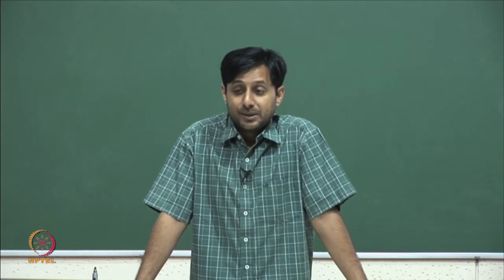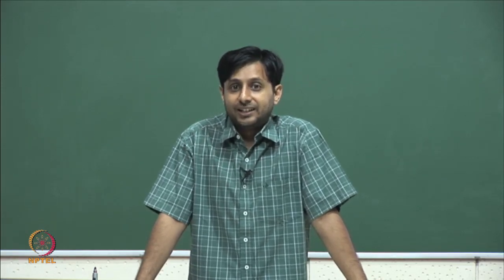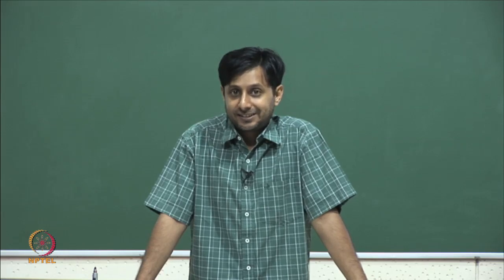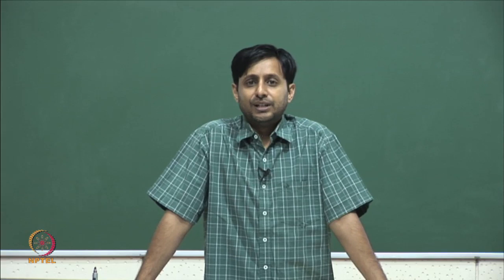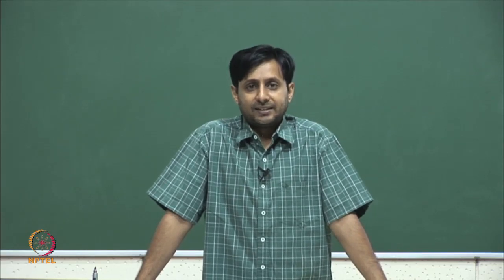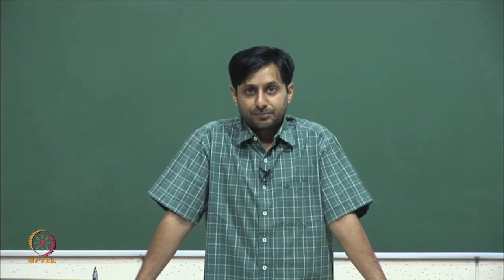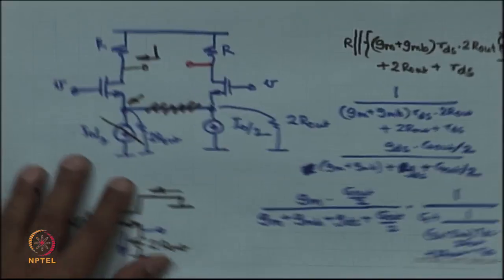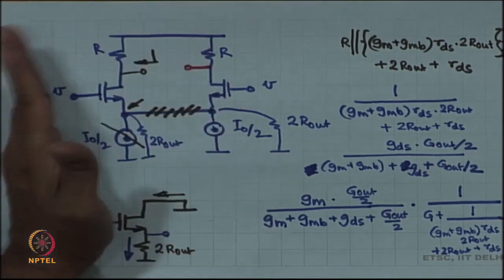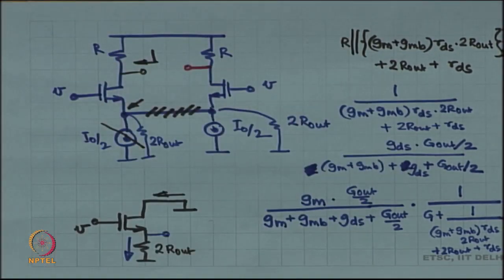Okay. So, once again the definition of common mode gain changes based on context. So, when you are in the lab, you are probably thinking of difference of two outputs by the average of the two inputs. Okay. If everything is matched, that is, if this half of the circuit is identical to the other half of the circuit, then the difference of the two outputs is 0.